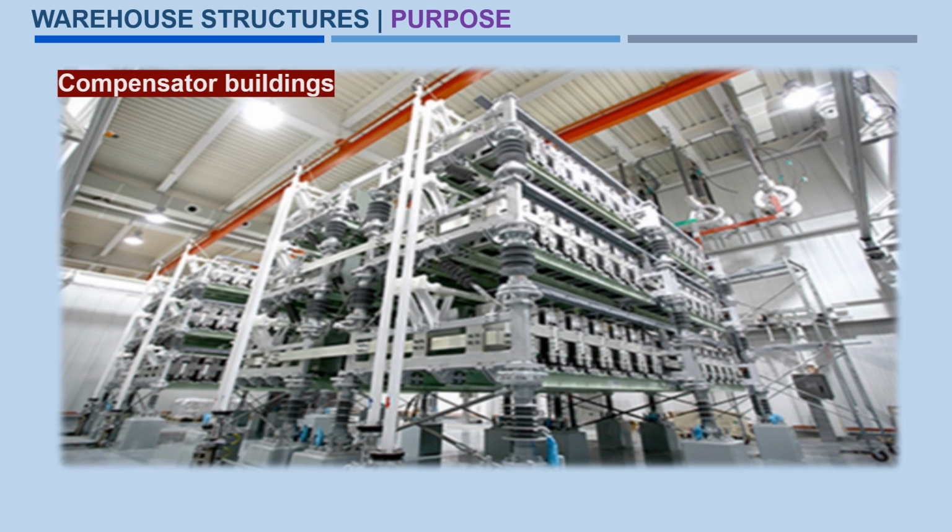Most of the time, fire resistant cladding is also suggested. Also while designing these compensator buildings, we need to consider fire rated steel structures, or the finishing or paints should be fire rated, and the thickness of the member size should be considered as per the fire rating.